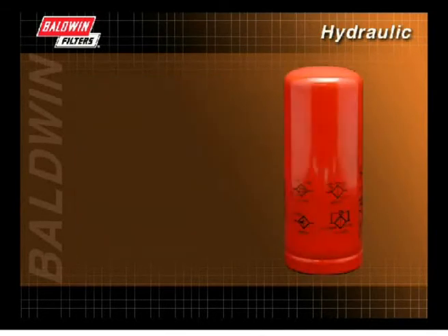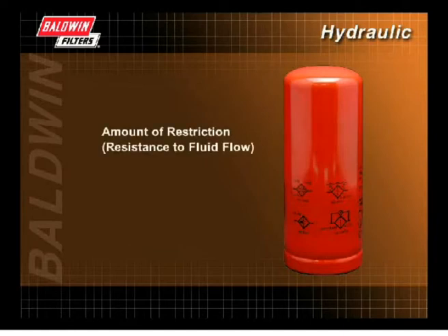A hydraulic filter also has performance requirements to ensure the filter meets or exceeds OEM and customer requirements. These requirements include the amount of restriction or resistance to fluid flow caused by the filter, and the amount of contaminant the filter needs to hold to meet service interval expectations.